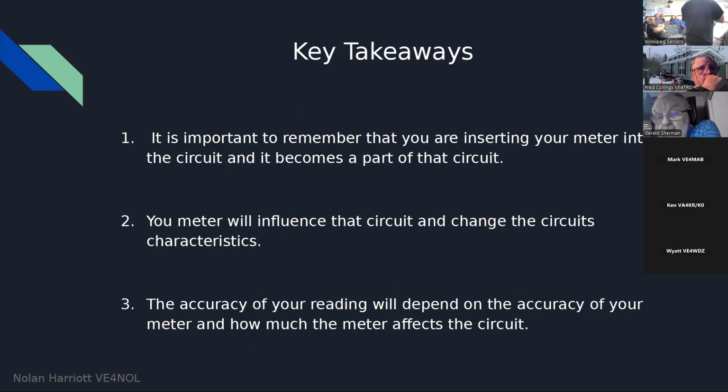Key takeaways. So to kind of sum this up, the point I was trying to make here is it's important to remember that you are inserting your meter into the circuit and it becomes part of that circuit. Your meter will influence that circuit and change the circuit characteristics, right? You are adding resistance into a circuit, no matter what, even on analog or even on digital meters, whether it's a much higher or lower resistance, you're still adding resistance into your circuit and you're changing the circuit characteristics.